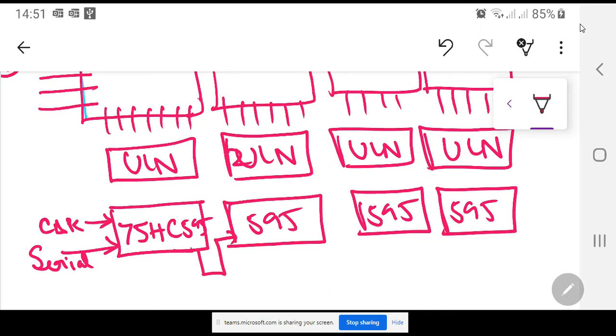Now in the same way, instead of having 8 pins here, 8 pins here, 8 pins here, 8 pins here, which requires so many resources from your microcontroller, what you are going to do is connect these 8 pins with this 74HC595 IC here, and similarly over here. You will give serial data over here based on the clock, just like your hard disk in your computer works or your USB device works. That works on a single wire or maybe 2 wires in the USB case.